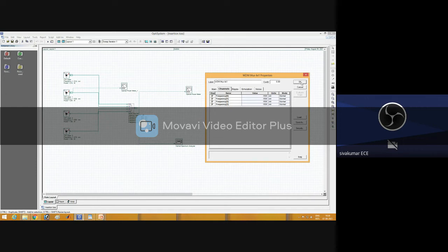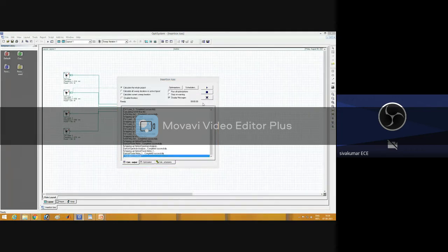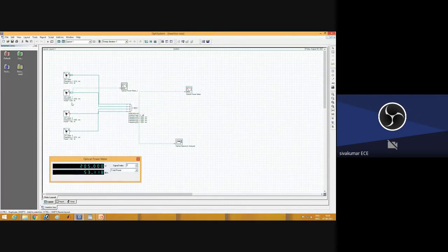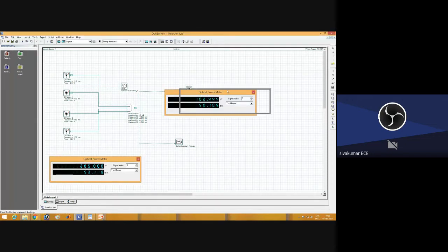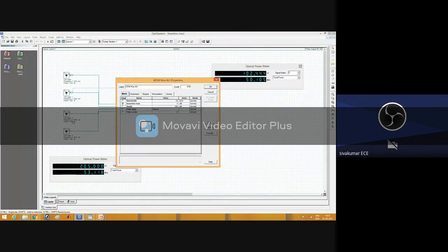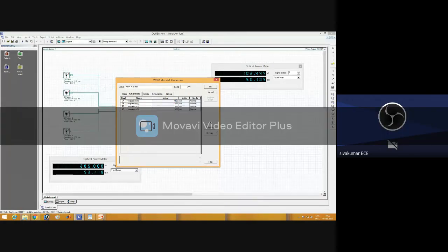Okay, now I think it is getting clear. Now after simulation, what is the optical input power? It is 205, because we are giving 205. Here at 1530, this is our output, 102.44. Okay, here if I want to change to 1550, I want to find the insertion loss at channel 3, that is the lambda 3 value of 1550. So in channels we change the values to 1550.